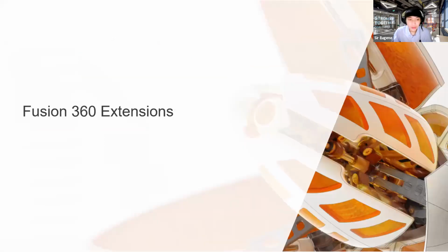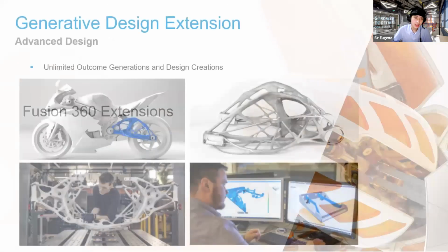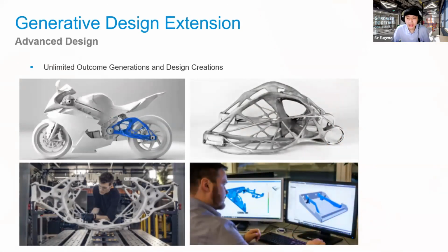Okay, so let's move on sa ating extensions, no? So Fusion 360 extensions. So first, we have the generative design extension. So as I've said kanina, yung generative design is gumagamit siya ng cloud credits to do study types or to do generative study as well as design creations, no? But with generative design extension, we will have the ability to do unlimited outcome generations and design creations without using cloud credits.